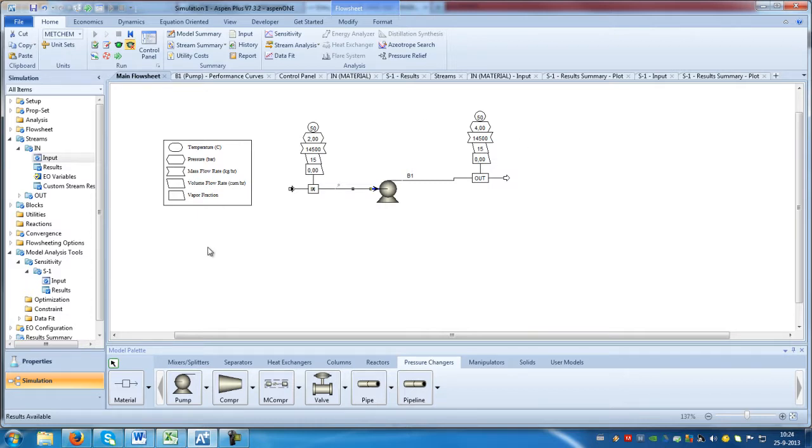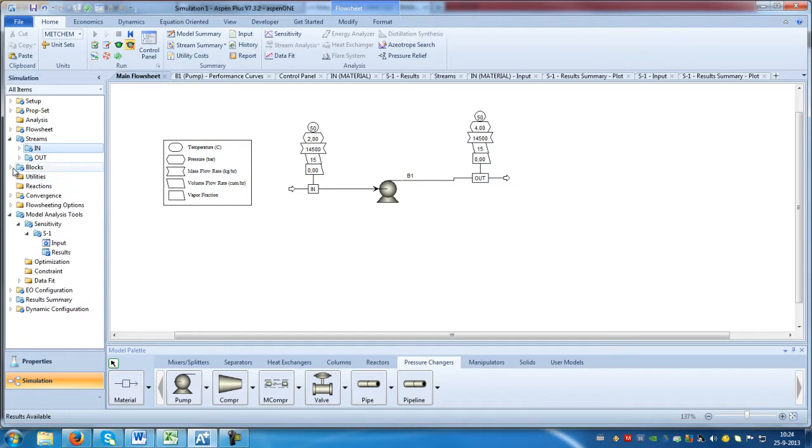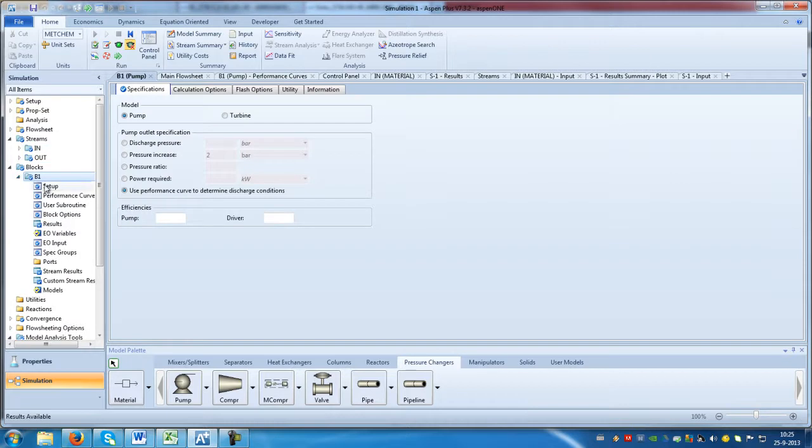Okay, so for my organic component, this pump wouldn't work to increase the inlet stream by 2 bar. I would have to choose another pump, but I think the way to do it is clear, so I hope you can also do this with your component, and choose the right pump. Another thing I want to show you is how to put in the efficiencies, and that is quite similar to putting in the performance curve.